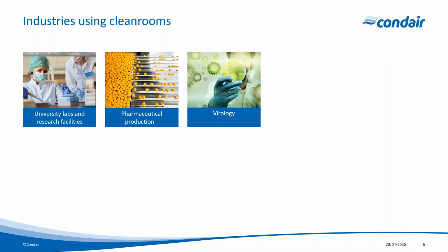Let's say we've got a series of blister packs that are going along a conveyor and they're being filled by dropping tablets into them. If we have a negative charge conveyor contacting a negatively charged packet, then we could get repulsion, and that can cause problems when you're dropping tablets into the packaging.